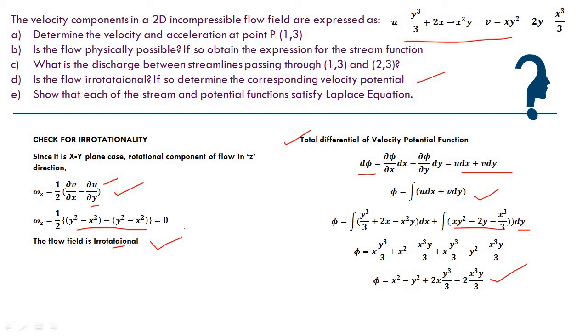The only thing is, for finding out these functions, stream function as well as velocity potential function, if the velocity components are given, we start with the total differential and substitute, and you should be thorough with integration.